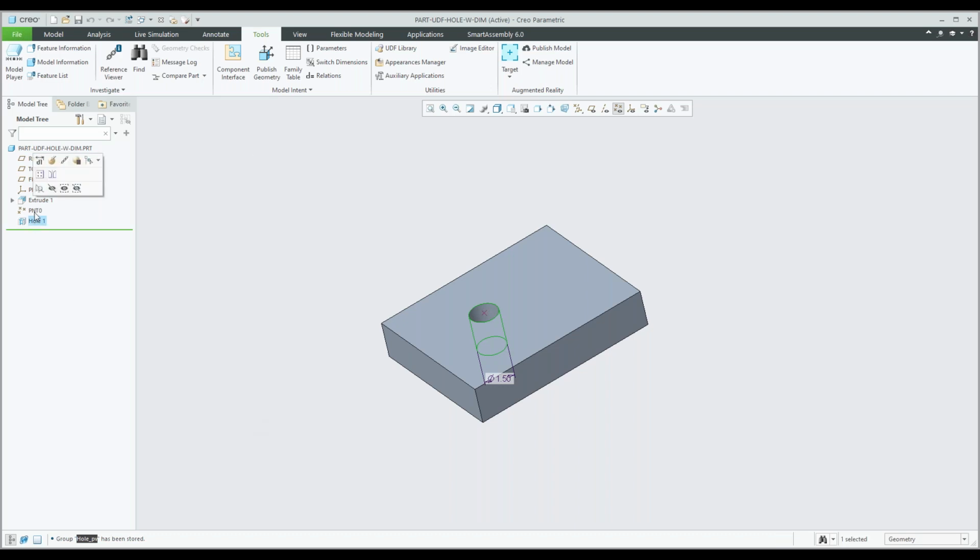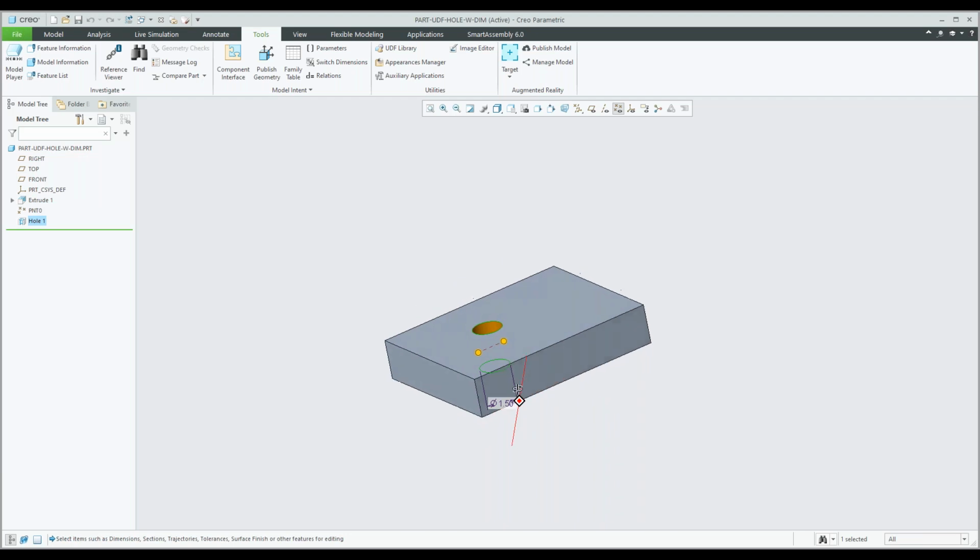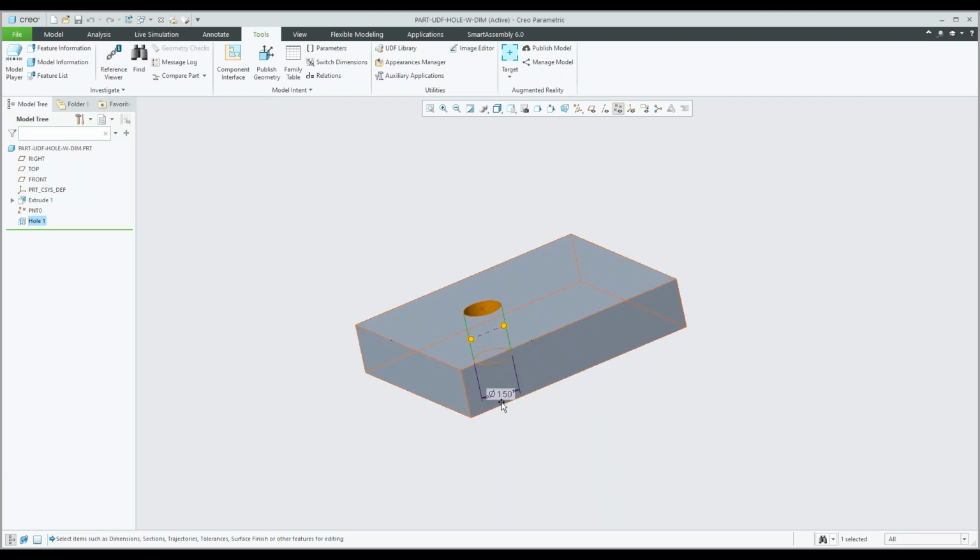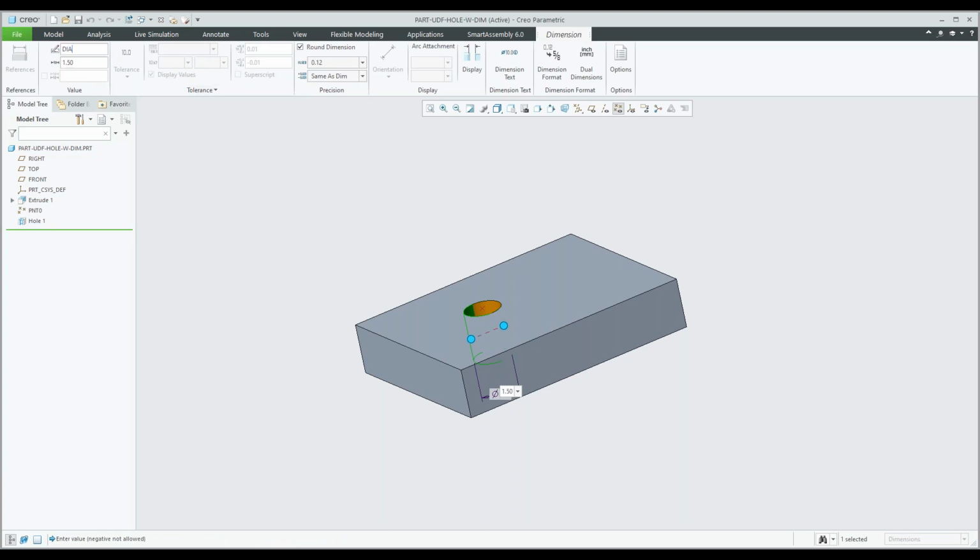Okay. So there was just one thing that I skipped here, and that is changing the dimension names. Just change it to something that makes sense. So if you highlight or show the dimension and you go to switch dimensions, you can see the name. So D9, that's not making any sense at this stage. And if you're going to take it to a program, that's even going to confuse matters more. So what you can do is just double click that, and I can just change that to something that makes sense. I'm going to name that diameter of the hole as well. Okay.